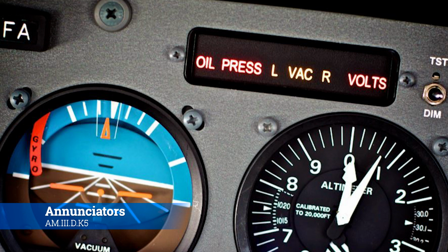The idea is that somewhere on the panel, you could lose, say, oil pressure or whatever. In theory, it's just a gauge that's moving, and you missed it because you're too busy talking or whatever the thing is. They wanted to have something that could actually get your attention, so it would light up and say, hey, look, you need to go investigate. So on this particular one, we have three annunciations, if you want to call it that, three lights that are illuminated.